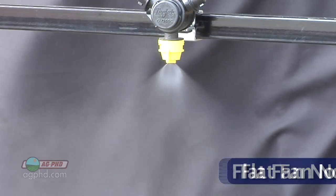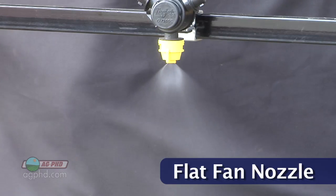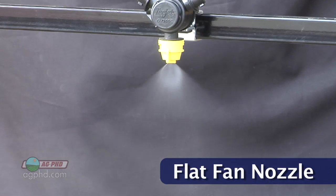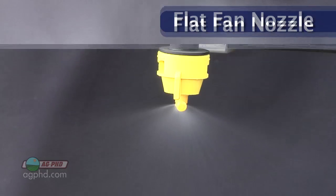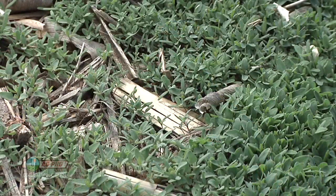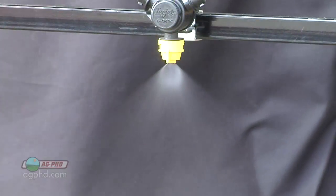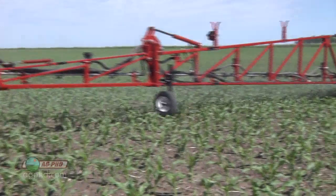So with the small droplets, if you want to just use an extended range flat fan nozzle, for example, you're going to have small droplets with that extended range flat fan nozzle, which is great for spray coverage, and sometimes you will get just slightly better control than using that turbo T-jet or air induction nozzle, where you'll have the bigger droplet. So what I'm trying to say here is, it's great that you want to reduce drift, but I want you to think about how many weeds do I really have in the field? If I only have a handful, I don't mind giving up a little bit of control. But if I have an absolute disaster in a field, then I want you to consider using that flat fan nozzle that has the small droplets and will give you more drift, but spray it on a good day.